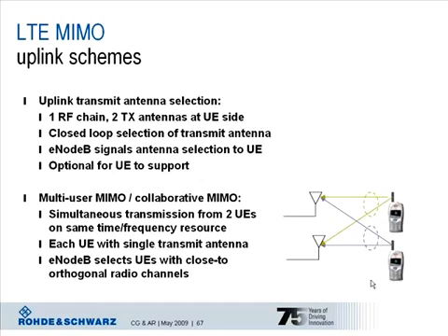Another scheme used in the uplink is the so-called multi-user MIMO or collaborative MIMO, supported in LTE, where two UEs transmit simultaneously over the same time frequency resources, as indicated in this small picture. The UEs are scheduled by the base station, so the base station needs to decide whether this is actually possible or not, and each UE just needs to have one transmit antenna in this case, as also indicated in this picture. But you can imagine that this scheme only works in certain radio conditions, so it's really up to the base station to evaluate that carefully.